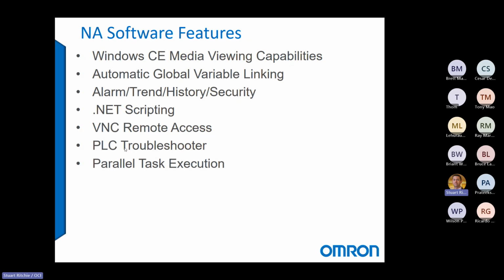And we have a tool built in the HMI called the PLC troubleshooter. So if you were online with a PLC that had a fault on it of some kind, in Sysmac Studio, we can open up our troubleshooter and it's going to tell us exactly what that fault is, and it's going to suggest remedial actions, that kind of thing. We can embed that into our HMI.